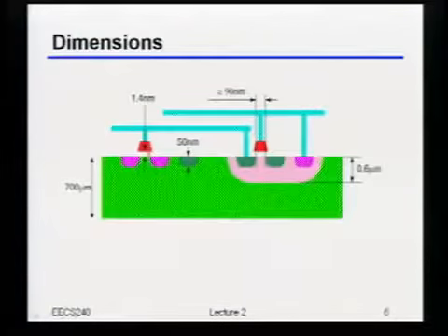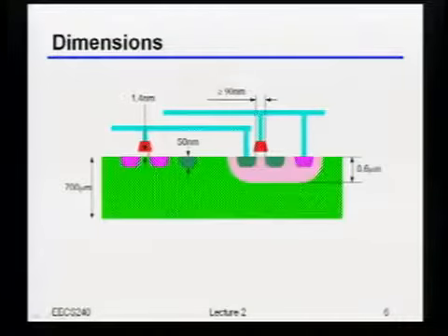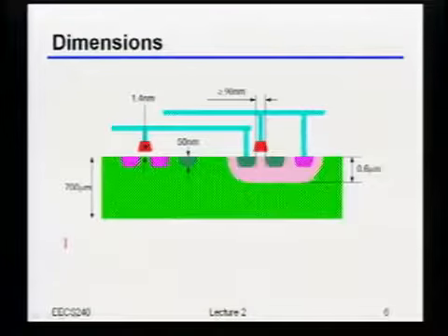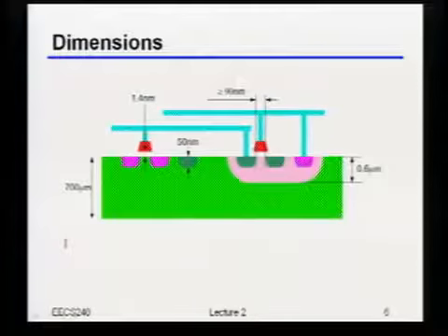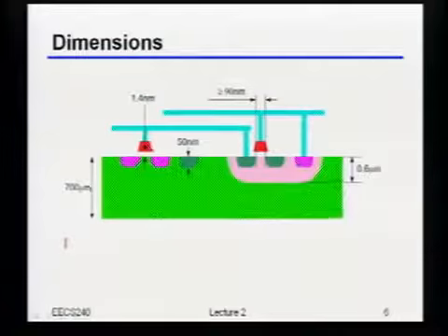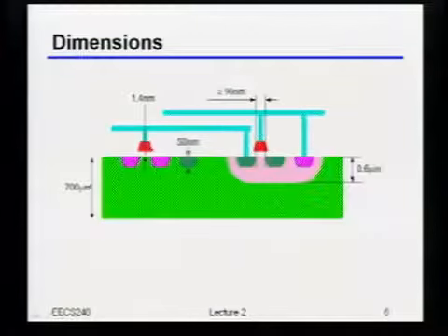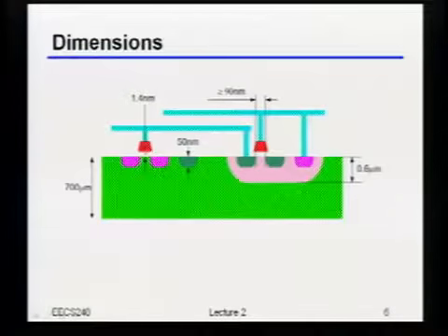Okay, so another thing to keep in mind. The other thing that's actually kind of interesting here, and I annotated this, if you look at a typical silicon chip, at least while it was on the original wafer, you've probably got a thickness of about 700 microns, maybe a millimeter or so. So notice, even though I could define these super thin features, like even this gate oxide of 1.4 nanometers, I've still got this pretty thick silicon wafer.